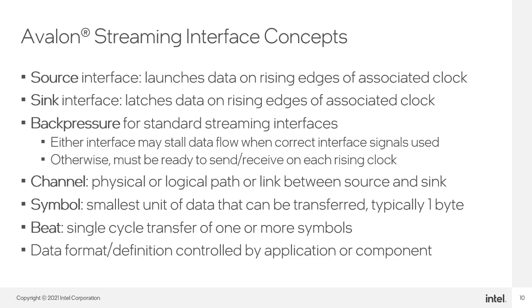By default, both interfaces must be ready to send or accept data every clock cycle unless additional interface signals are implemented to stall data transfers and implement flow control. Back pressure is the term used for this flow control mechanism. Both the source and the sink can stall a transfer using the appropriate signals.